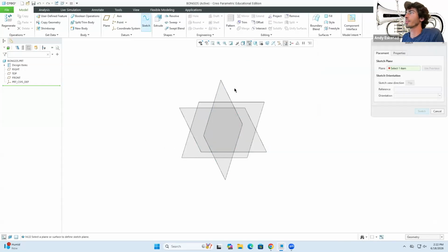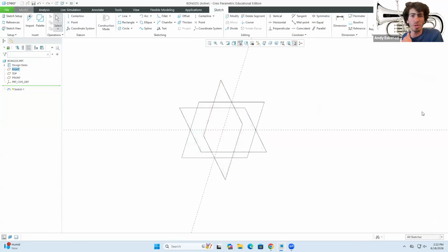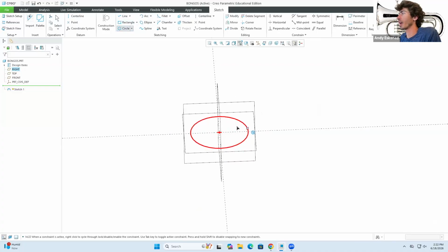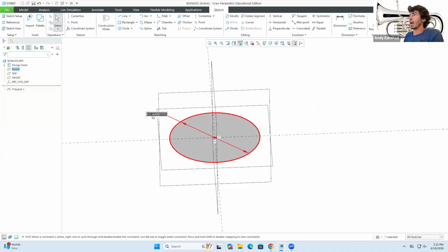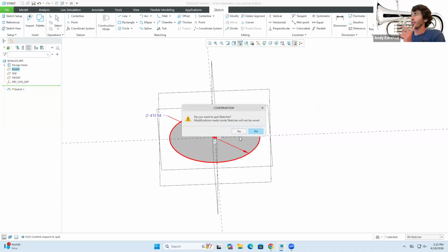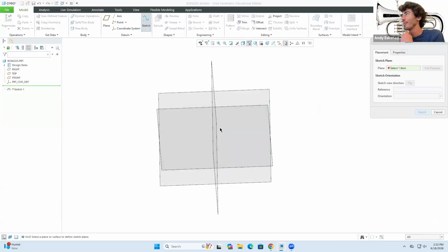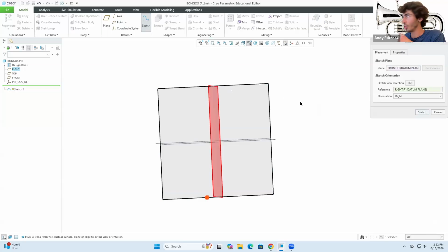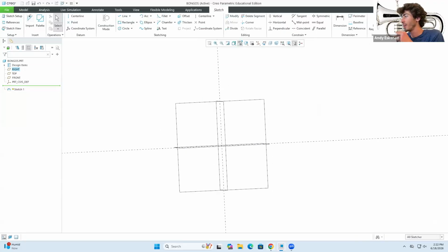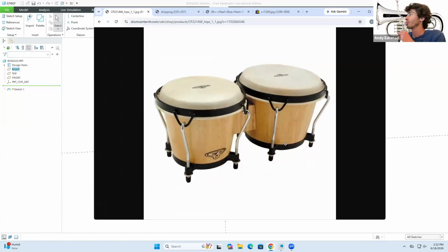So I'll go here to Sketch, over to this face, and here we're not gonna really use an image. I think we can eyeball most of this stuff. So I'll do a circle, and actually, an even better approach than this, yes, I'll sketch. I'm gonna do a revolve from the beginning. So I'll start maybe from here, doing a sketch in this face. And you can see that goes straight, then it's tilted at an angle, and then it comes a little bit to the side, and then there's a little bit of protrusion in there.